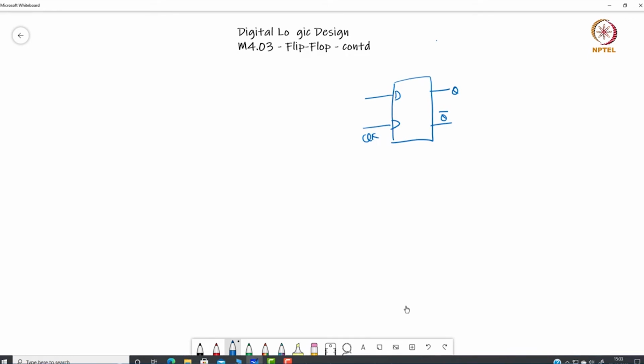Now to avoid that, can we do something like if we want only during certain period of clocks, then we want this D to be transparent, otherwise we don't want. So then we can also gate this clock. So this is my regular D flip flop. I can create a gated D flip flop. One of the ideas of a gated D flip flop could be something similar, like let's say I have this value of gate and I use this clock, and then I use this as an input to my regular clock.